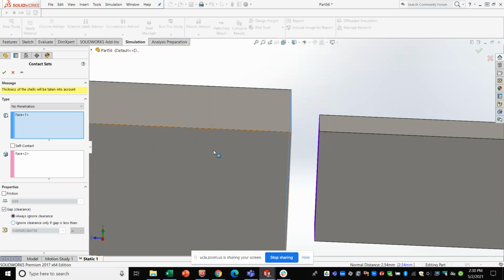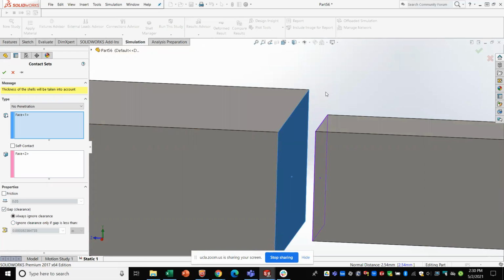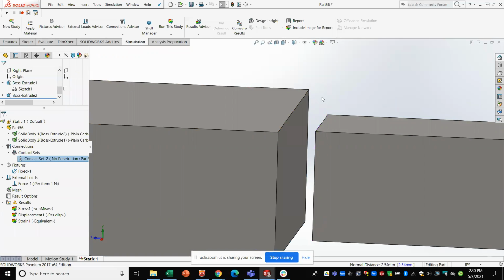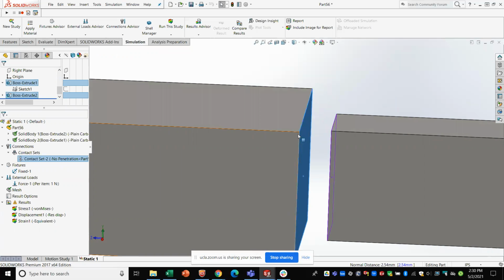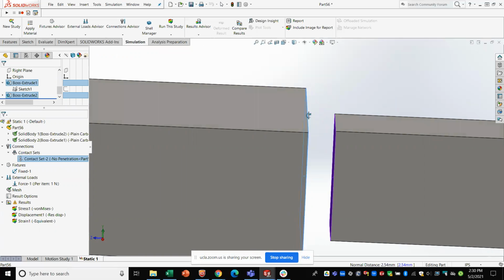Basically, it'll figure it out for you, but I want you to offset those triangles by a certain amount so that they do touch. So what will happen here is all those invisible triangles, this part has a 1/10 of an inch gap. Those invisible triangles are going to offset from the surface by about half that distance so that they start touching.